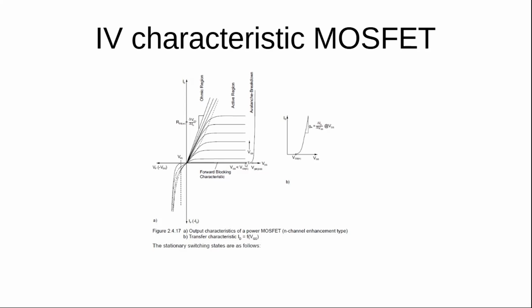You're not going to take any power diode and apply 1 kilovolt to it. Chances are if you apply 1 kilovolt, it will fail. It will go into avalanche breakdown. Same thing, of course, happens on the negative side also. If the negative voltage is too big, it will still break down. It will fail.